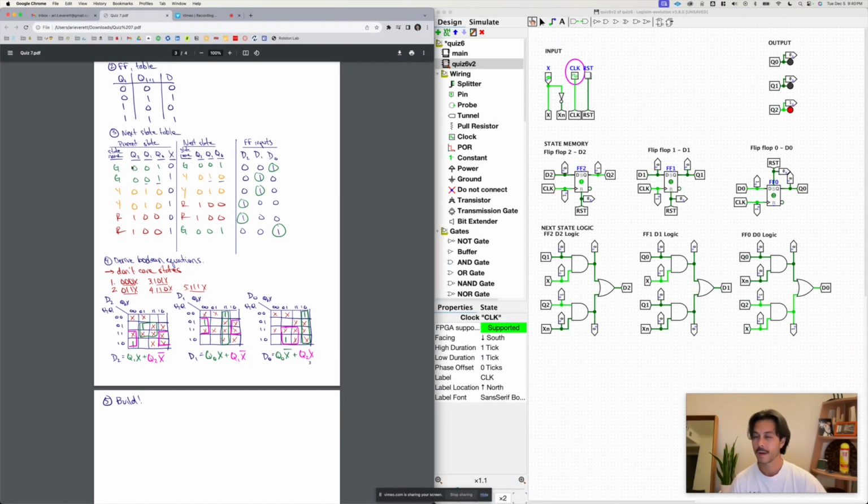Since we have now 4 digits, or a 4-bit input for a K-map with the X input and 1, 2, 3 flip-flops, that leaves a lot of don't care conditions that we didn't list in the table because we don't care about them. Those states are not used in the one hot encoding. So 1 here, for example, is 000 and then a don't care within the don't care. So 0001 and 0000, you can see from up in this table, is not used at all.